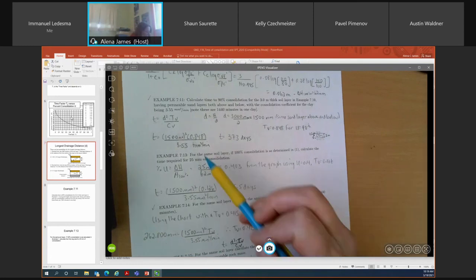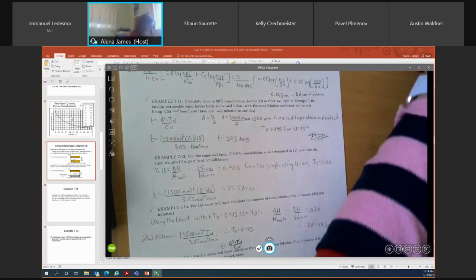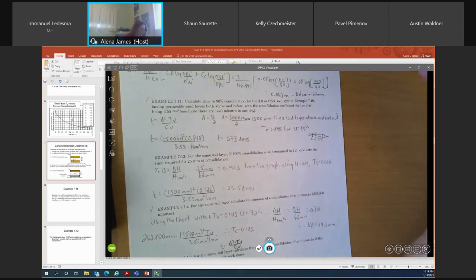So my TV value is 0.848, and then I divide that by my CV value. So I calculated 373 days, but if you were to calculate in minutes, you would calculate it initially in minutes. You would get 537,465 minutes. And I just converted that to days by dividing by 1,440 minutes in a day. And I was able to determine it was going to take 373 days for this 90% consolidation to occur.